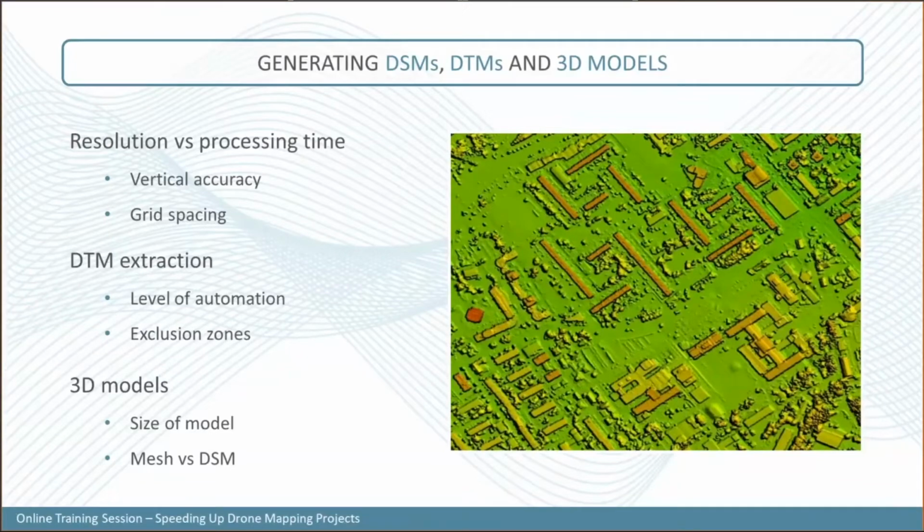But you should be able to get the best detail possible for your drone project. We suggest not going lower than 3 times the ground sample distance. Otherwise, you may raise the processing time too much, and there's not a significant improvement in the quality of the output between 3 times and 1 time the ground sample distance.